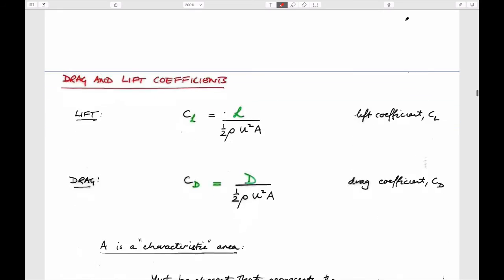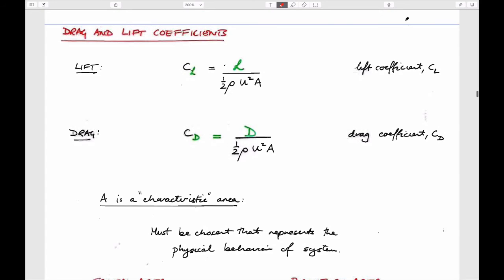We talked about ways of being able to calculate either lift or drag. By convention, we've said already that this is basically an Euler number with a half in it. So you could rewrite this as an Euler number where this is length over area divided by a half rho v squared. This term doesn't belong in an Euler number, but this is basically a pressure of lift or a pressure of drag. And we can define the lift coefficients or the drag coefficients in terms of this.